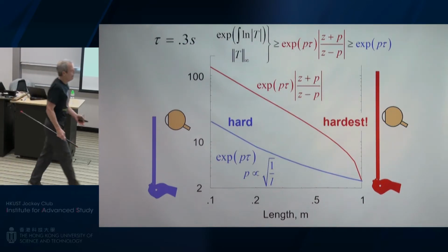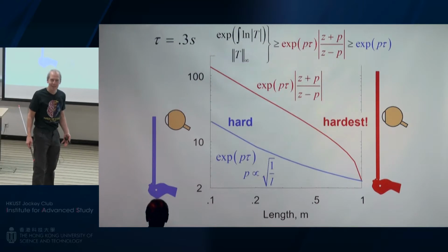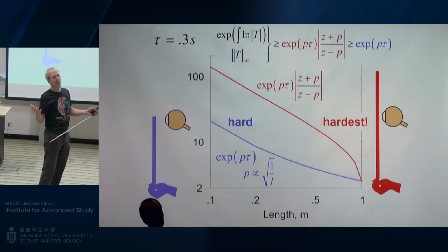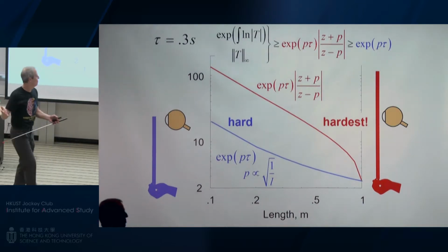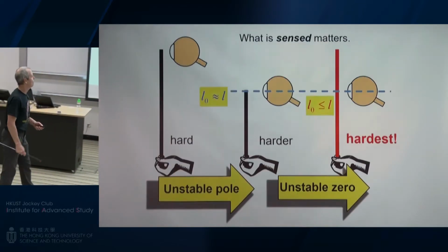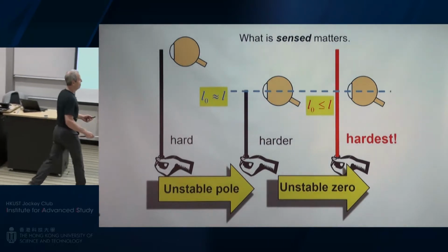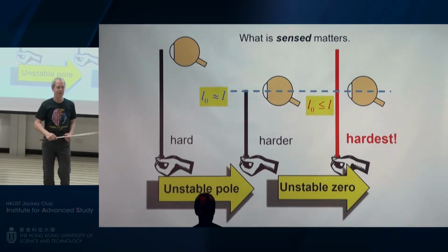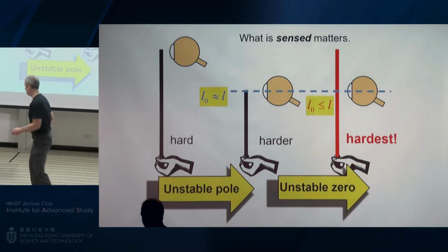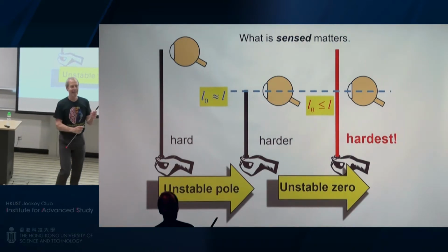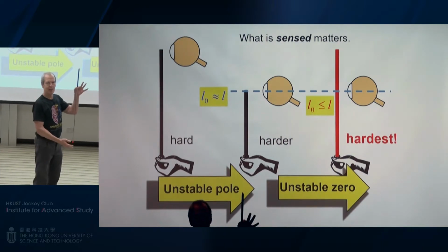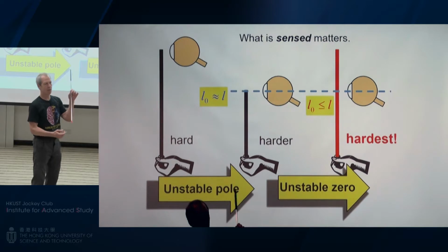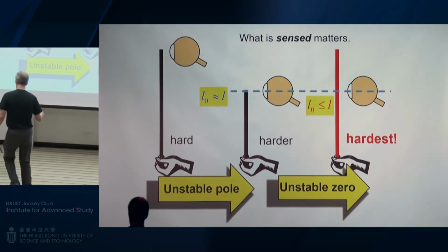And also, why do we talk about the frequency domain, right? Now, this is me talking, right? I've been loving the frequency domain again for more than 40 years, but this is not the way to go. Anyway, this is an unstable zero. So if you want to teach unstable zeros, this is the way to teach it. And you can even explain what a zero is. Because what a zero is the dynamics if you pin the point you're looking at. So one of the reasons this is bad is you get an unstable zero. Anyway, you can do all sorts of cool stuff with that.